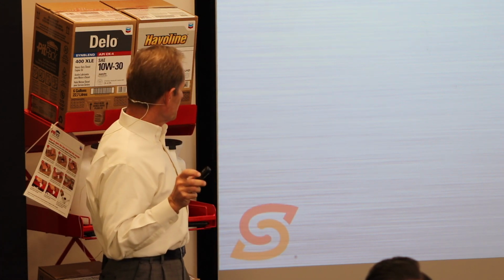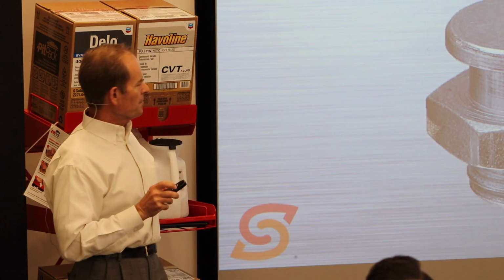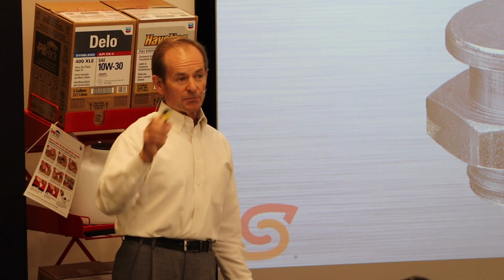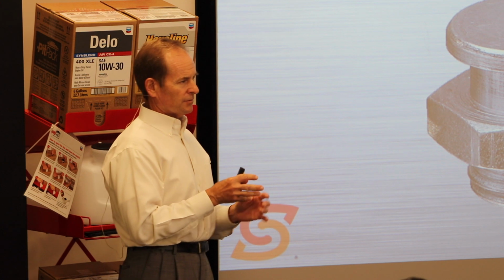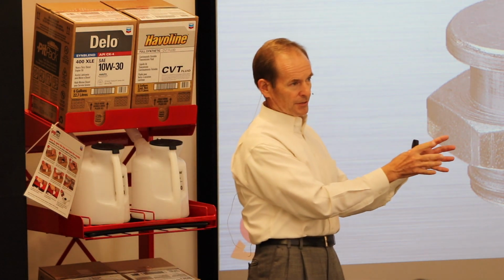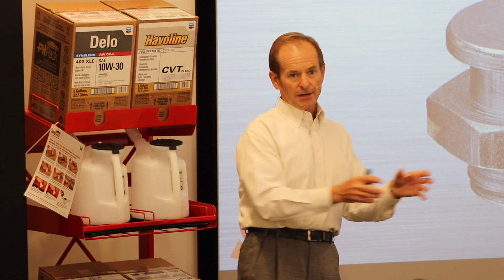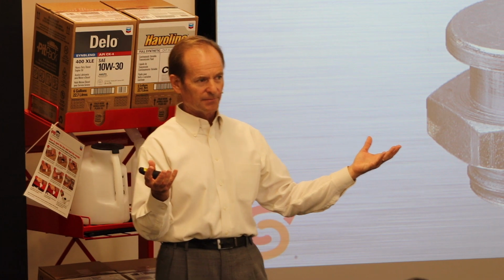Another practical grease issue that I like to spread the word about. In a given plant, frequently they're trying to use as few greases as possible. And you often come down to something like one grease for electric motors, like a polyurea grease, and then another one that's a general purpose lithium complex grease. And polyurea and lithium complex greases are seldom compatible, we'll just say it that way.